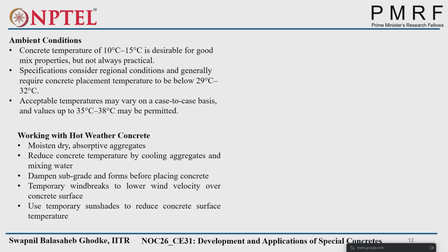So working with hot weather concrete. For that purpose, what we have to do: moist and dry absorptive aggregates, reduce concrete temperature. So how will we reduce the concrete temperature? By cooling aggregates and mixing water. These are the two impactful factors: water temperature and cooling aggregates.